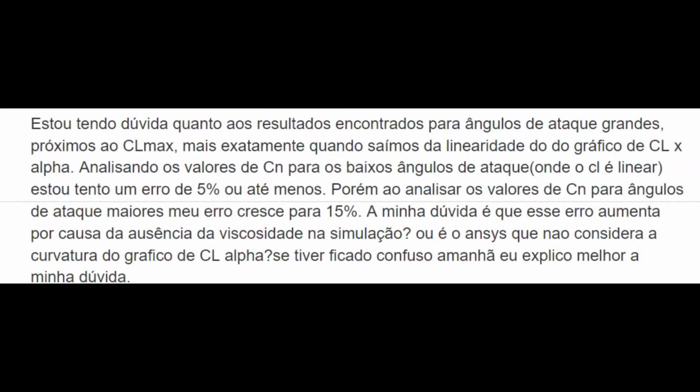No, I adapted it, as I already showed in the previous video. I can give you the link to the previous video where I show how you calculate the size of the airfoil to correspond to experimental data in terms of the Reynolds number. So we have the same Reynolds number in experiment and in the simulation. But to have the same Reynolds number in simulation, you can change only two parameters.